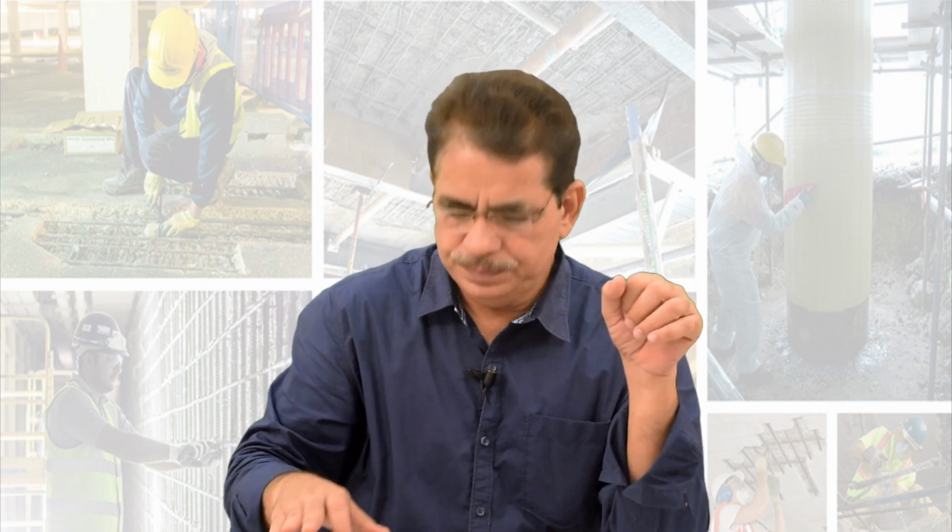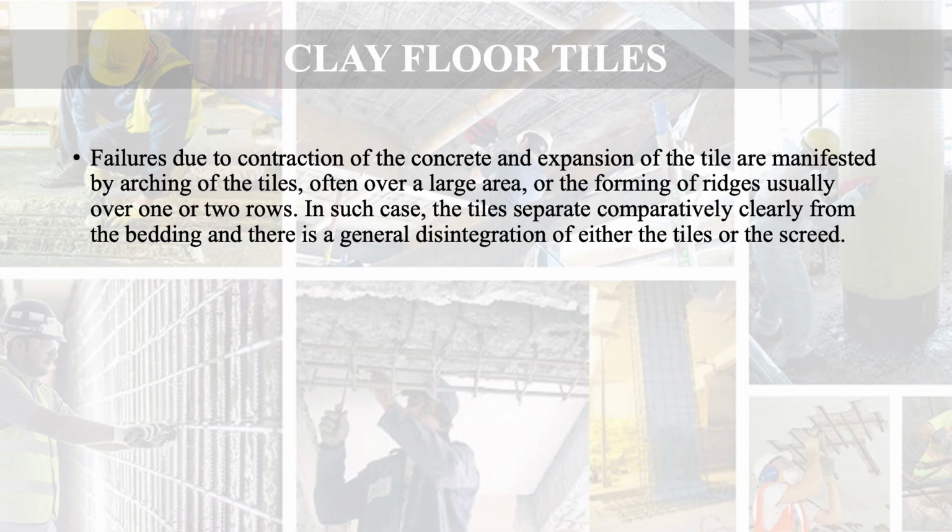That is the problem. Failures due to contraction of the concrete and expansion of tile are manifested by arching of tiles, often over a large area, or the forming of ridges usually over one or two rows.